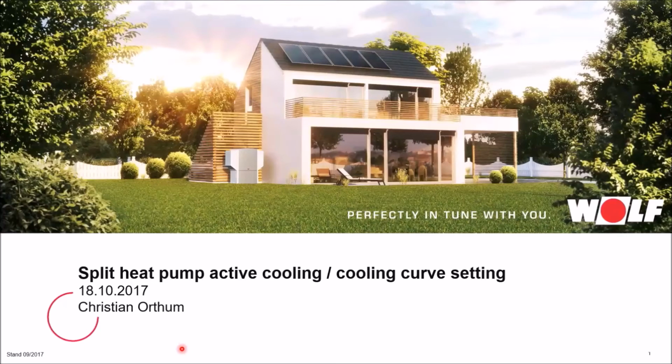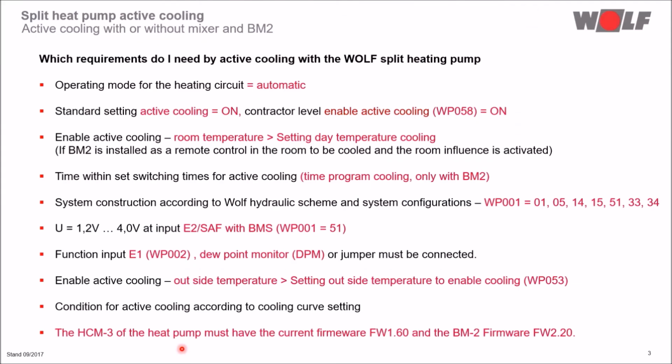Hello and welcome to this webinar with the topic Split Heat Pump Active Cooling and Cooling Curve Setting. In the first step, we look at the requirements which are needed to program the active cooling of a split heat pump. The operating mode for the heating circuit must be switched to automatic.